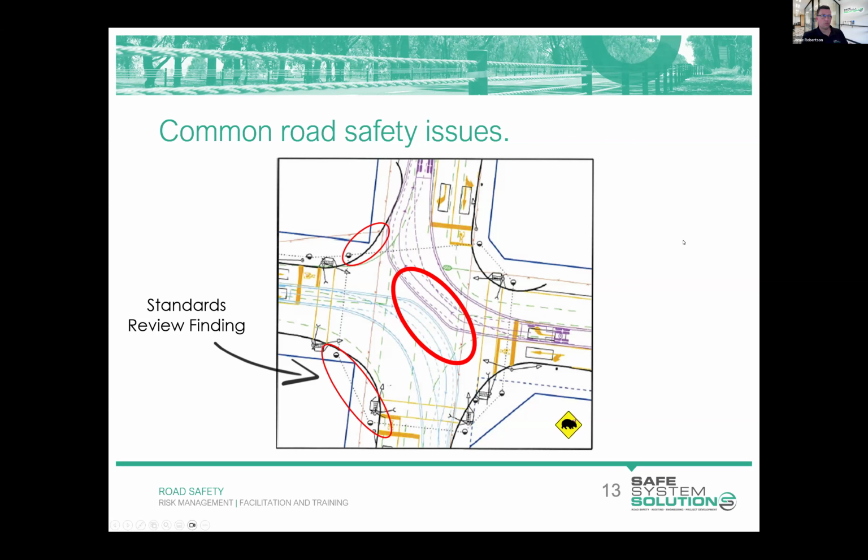You potentially could adjust signal phasing to ensure that the conflict between the right turns doesn't occur, or at least the likelihood is minimized. You wouldn't expect two trucks that arrived concurrently to continue into a collision situation. They would take some evasive action if the space wasn't there, but that might have some flow-on effects.